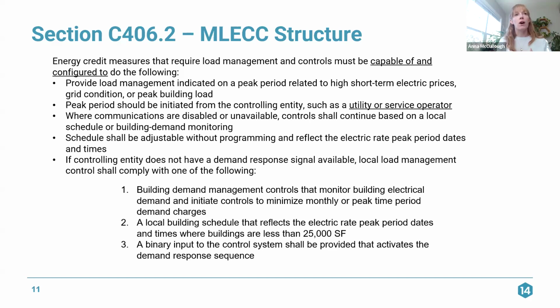But we don't have requirements around the use of those pieces of equipment. This section does require it. So if we are using the load management credits to achieve the credits required under section C406, you do have to configure that equipment to actually reduce the peak loads in the building. You don't get credit for just supplying them because they're already required as part of the base code.